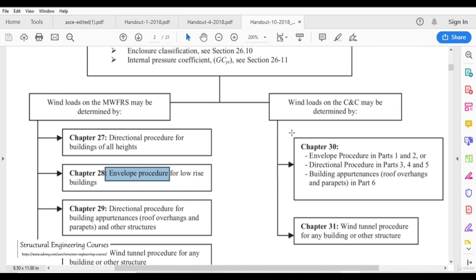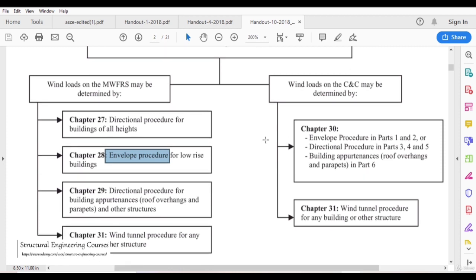For all those wind loads, if you talk about the British standard, I think it was BS 8007 if I'm not wrong. The BS is a superseded code and is not used nowadays, because the British are also following European standards with the British annexure. If we talk about the European codes, the loadings are given in EC1 if I'm not wrong. For the Indian standard, it is given in IS 875 part 3 for wind loading.